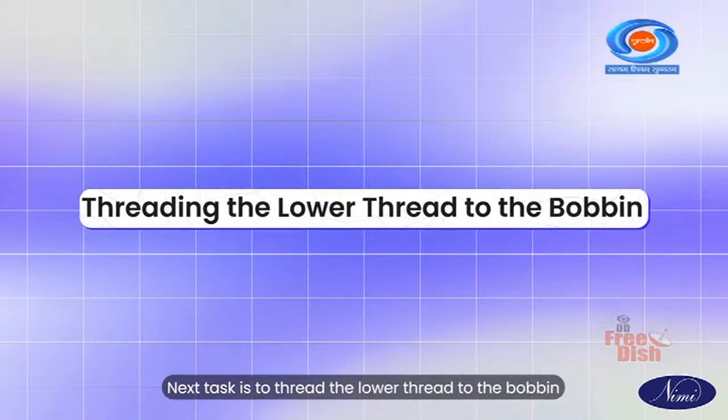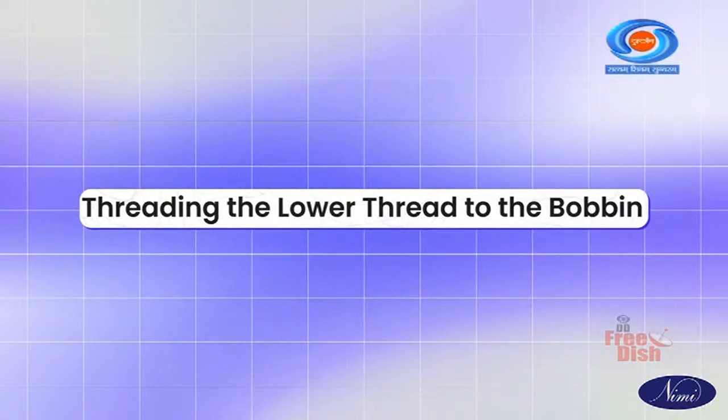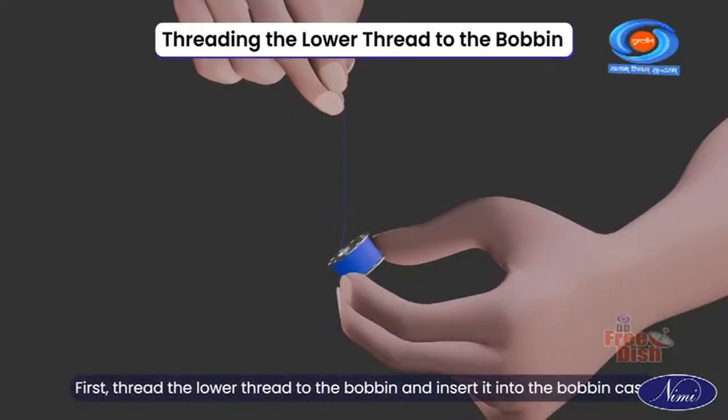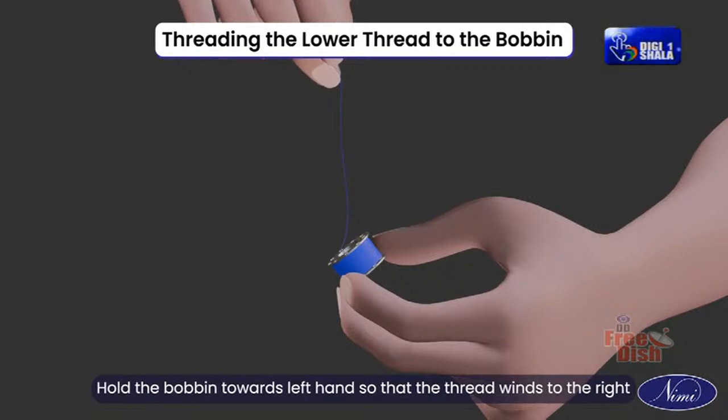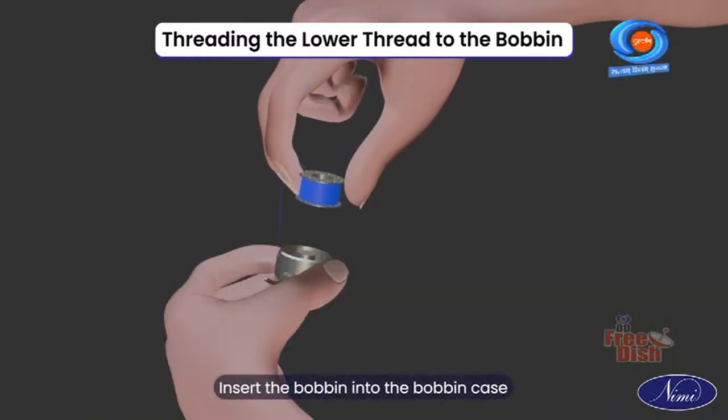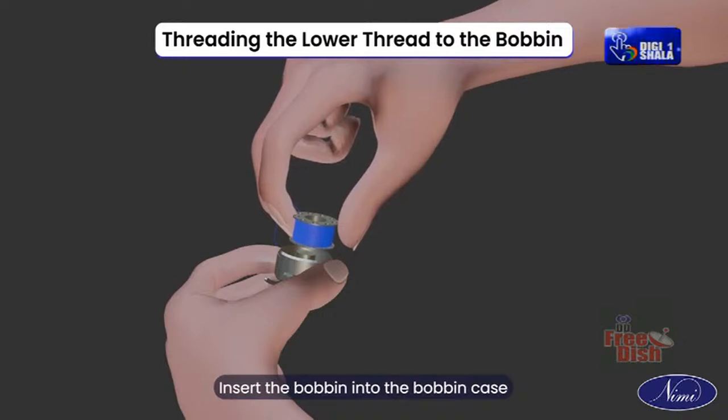Next task is to thread the lower thread to the bobbin. First, thread the lower thread to the bobbin and insert it into the bobbin case. Hold the bobbin towards the left hand so that the thread winds to the right. Insert the bobbin into the bobbin case.